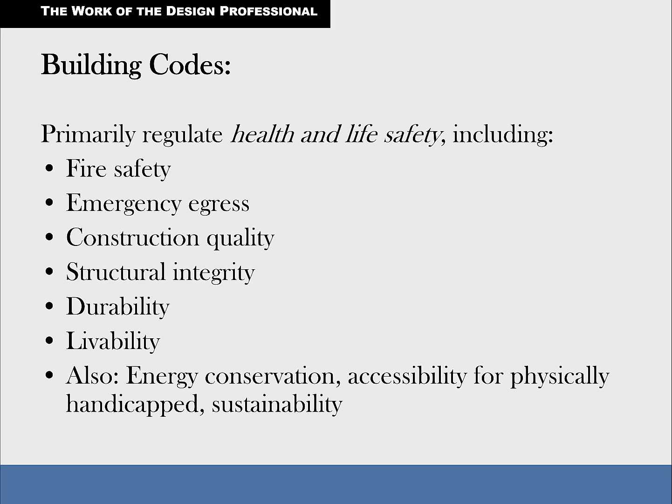They also regulate construction quality, so structural integrity and the durability and livability of the building. So there are things that they test for, including making sure that you've got proper insulation, that you've sealed the building up, and those kinds of things. Nowadays they'll actually pressure test your house to see how leaky it is, and if you don't pass that inspection, you don't get your final occupancy permit. And that's something that never happened in the old days. Houses were meant to breathe, we say. Well, energy costs and such have made us think that through a little differently.